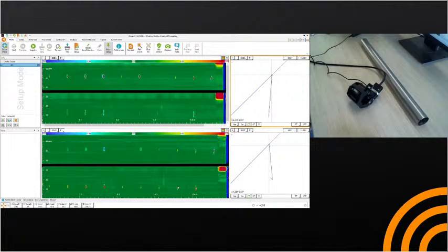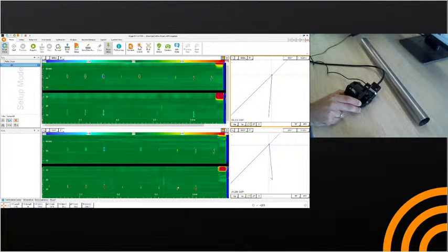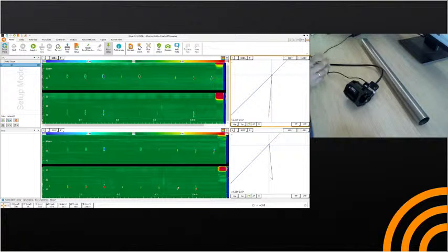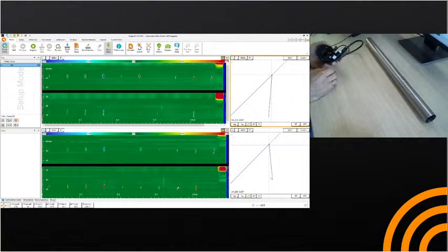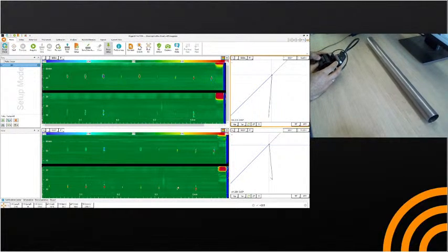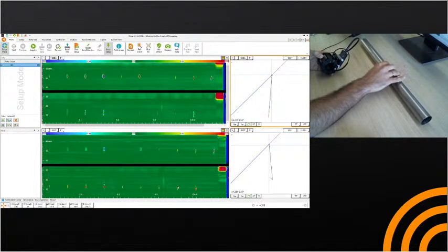So without doing any adjustment, we have good data quality. Why? Because we are using the pipe scanner, and this pipe scanner will always keep it stable. So during the scan, any movement like manipulation variation won't be here because you have the iFlex that will be fixed tightly to the surface you are inspecting.